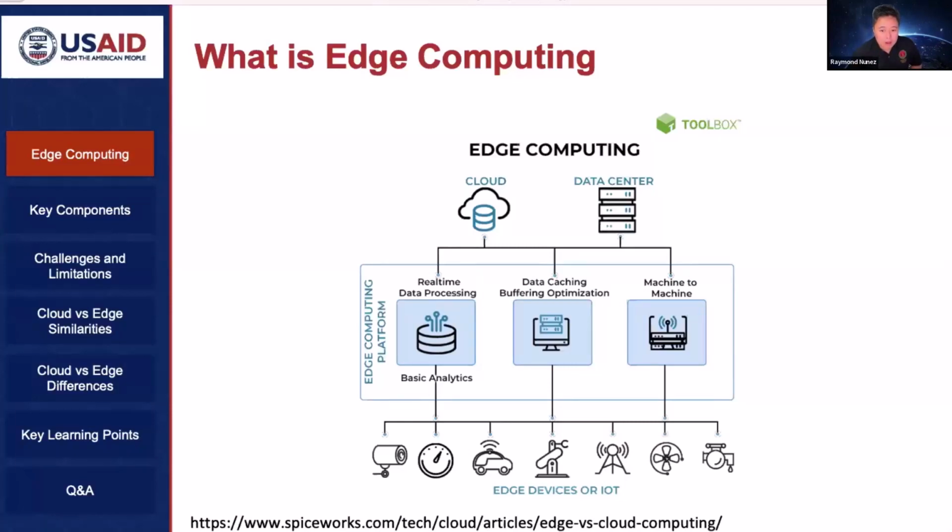Now, while in theory you could have that sensor send that data to a central cloud infrastructure and have that cloud collect all this information and then decide whether to open the valve, on some real-time decision-making points that might take quite a bit. It might be in the milliseconds, but that would still be an issue on real-time systems. So you would want that sensor to also be able to decide, based on what it was programmed to do, to either open the valve or continue operating until a threshold is reached within itself, and just report that action and data collection to the central platform.